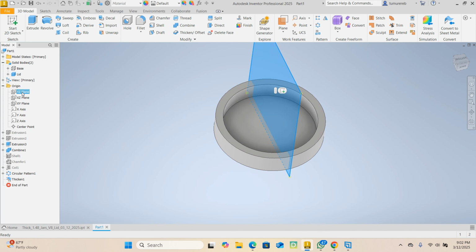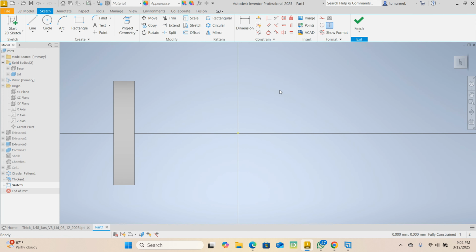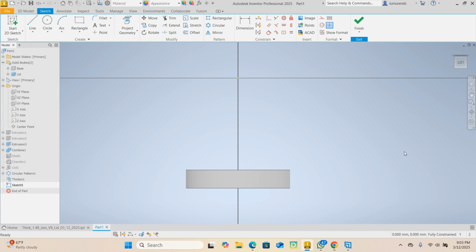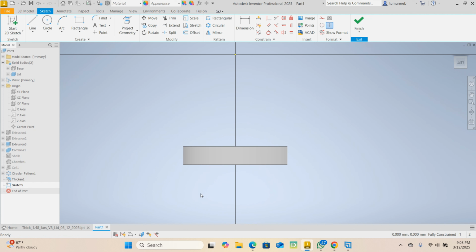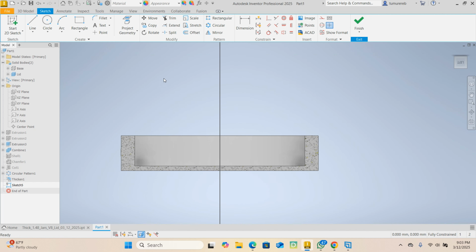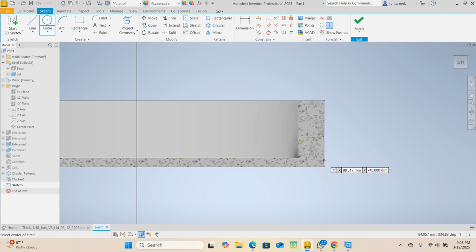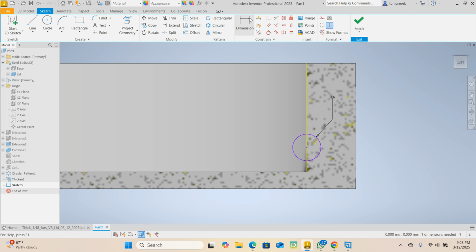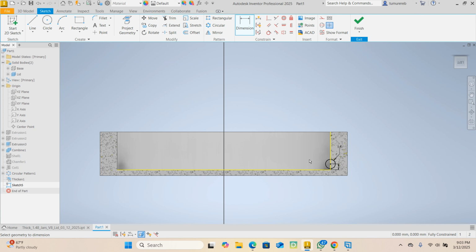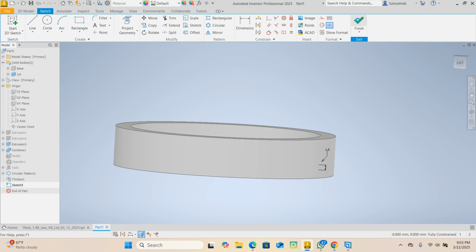Next, select YZ plane. I want to rotate this. Okay, so I'm looking at it from this view. Now go ahead and do slice graphics and draw a circle again. This time we want to draw it inside. And the radius is going to be 1.6. Why did I do 1.6? We need to add a small gap tolerance. Alright, so 1.6. Distance is the distance from the center to this point. Let's make it 2. Fantastic. And finish.